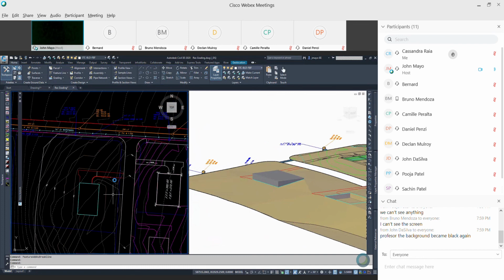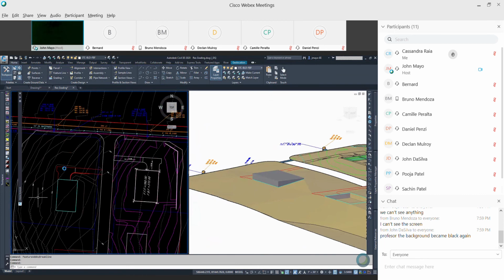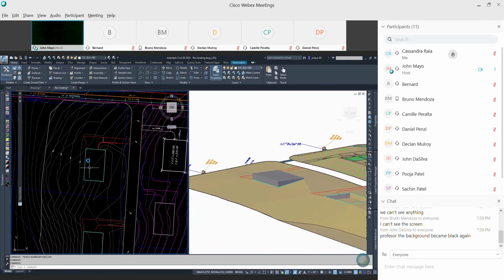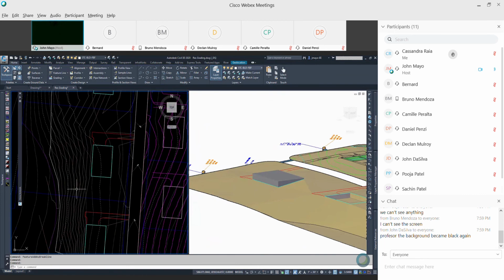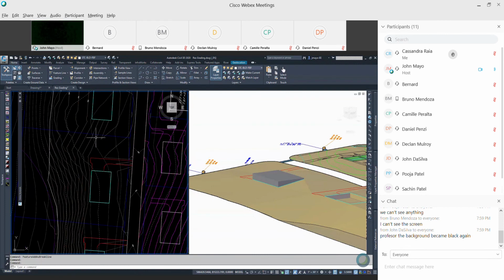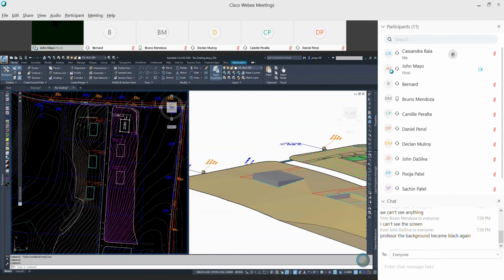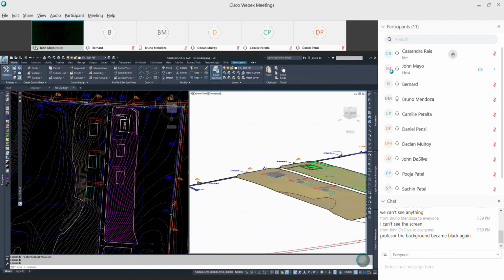And it looks pretty reasonable. I could later on take these contours, and we'll get to that next week, draw polylines over them to smooth them out a bit. But before I do that, I want to move on to my next lot's grading. And I want to see how these contours between the two buildings will react before I start putting in swales or retaining walls that I might need to make this work.